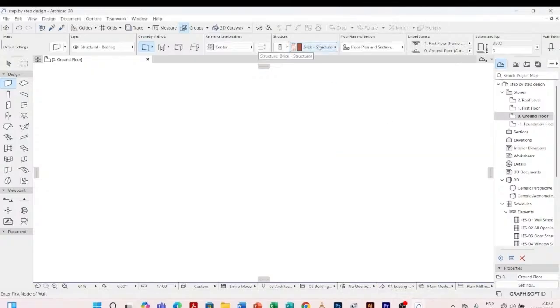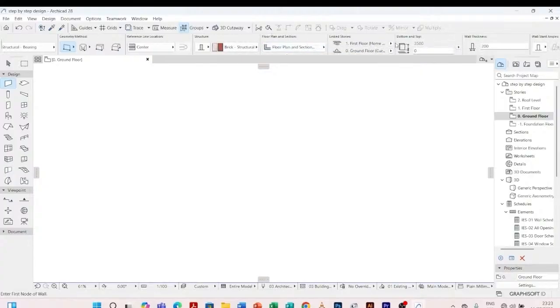So I click on it, it's ready. We have then here floor plan and section. These up here are all wall settings. So plan and floor sections, these are basically 2D visualizations, how we want to visualize our plan in 2D. That is on the floor, 2D in the sections, elevations. Then these are story settings, we have set them.